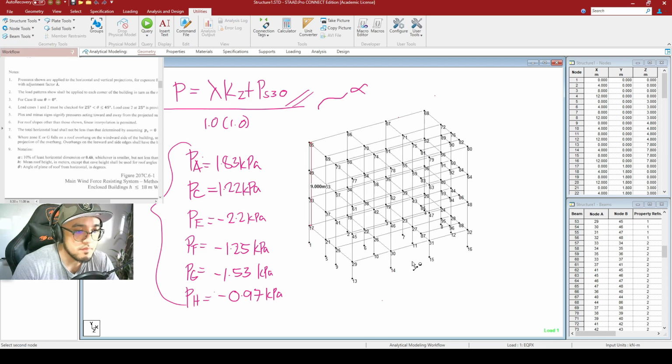So this is to be for your longer horizontal dimension, and that is to be 12 meters. And the least horizontal dimension is to be 7.8 meters. So 12 meters and 7.8 meters. Self-explanatory that the lower value here is to be 7.8 meters. Your alpha is to be equal to 10% of the least horizontal dimension, or let's say, I think it is better if I would be writing w here, for the width.